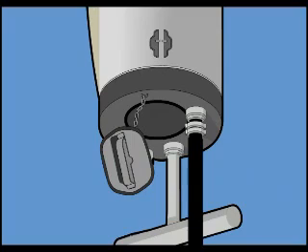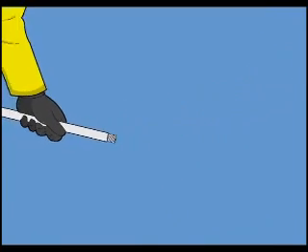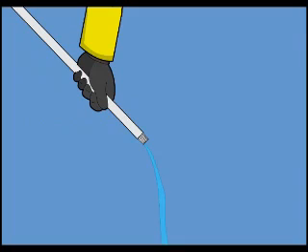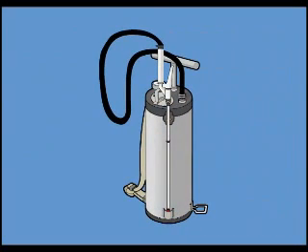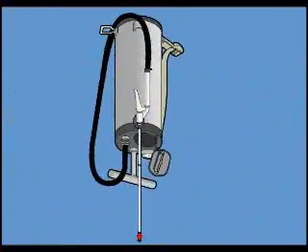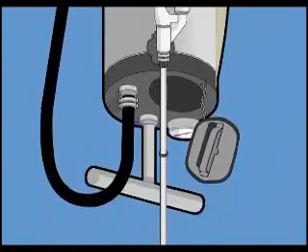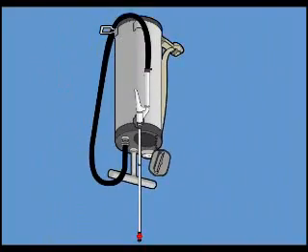With the lid open, turn the tank upside down, open the on-off valve, and let all the water drain out of the hose and lance. Ensure the lance is parked to protect the nozzle when not in use. When storing the sprayer for a long period, hang it upside down with the lid open to allow air circulation. Allow the lance to hang from the D-ring on the tank with the trigger valve cap open.